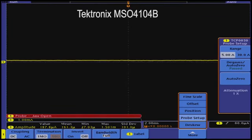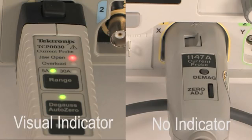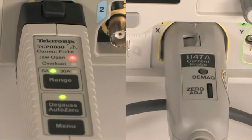Also important is the ability to know when the jaw of the current probe is fully locked. If not properly locked, the current measurement will be inaccurate. The MSO 4104B measurement system provides an indicator that tells users if the jaw is open. The Agilent MSO X 3104A system does not provide that same active feedback, which could lead to user frustration.